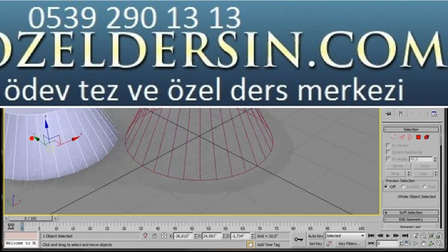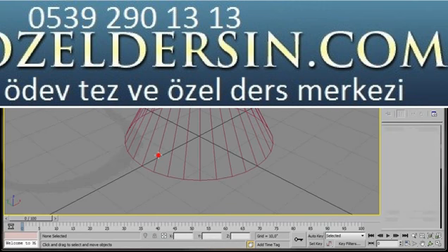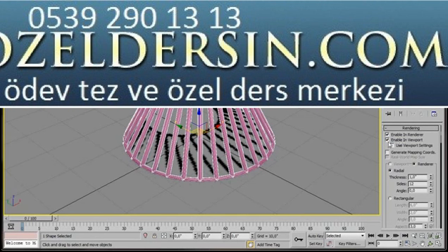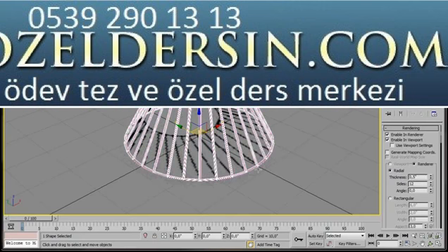Let's just move the original cone out of the way. We can delete the cone. There's just a few things to do now, so we'll select the shape, come over to the Modify panel, and here in Rendering, we'll turn on Enable in Renderer and Enable in Viewport. Now if we rendered, we'll be able to see our shape. Let's scroll down a wee bit more now. We'll go to Thickness, and let's bring the amount down. We'll bring it down to 0.5.